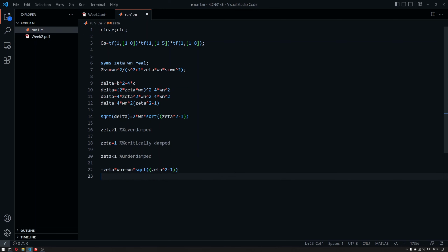So, since we have only the limitation of settling time, we can just directly try to pick a settling time for this system. Now, usually we would start with an overshoot value and a settling time value. Then, since the overshoot itself is zeta related and the settling time has zeta and omega n, we have two identities for two unknowns. Therefore, we would just directly calculate a corresponding second order system.